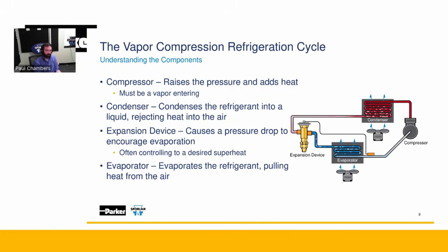An important thing to know about compressors, and I've tried to drill this into people. I've met some people that really want to try the opposite, and it doesn't work well, is it must be vapor entering that compressor. If you worked on cars, you think about liquid hammer. It happens on cars, it happens on compressors. If you think about taking water and trying to squish it down, you're not going to be able to squish it. But if you had a syringe of air in it, you can squish it down.